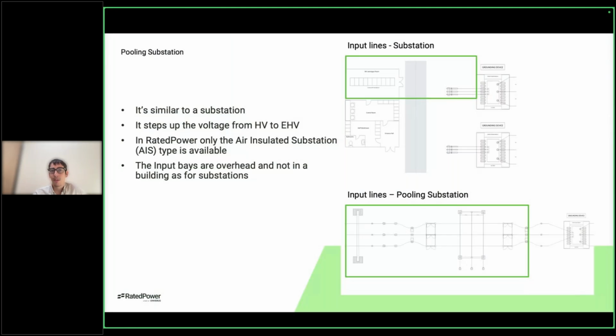Another type of substation possible or available in RatedPower is what we call a pooling substation. And I mean, it's similar to a regular substation. The only difference is that it steps up the voltage from high voltage to extra high voltage level. And again, in RatedPower, only the air insulated substation type will be available. This helps us to connect or adapt our projects in a flexible way, creating different types of schema for the interconnection facilities and having a pooling substation that evacuates all of the generation.